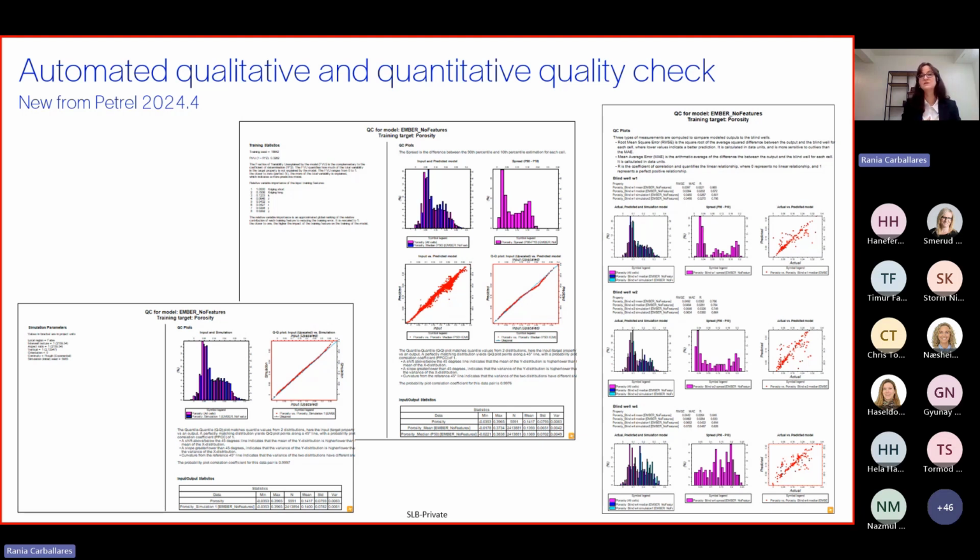We try to open cross plots and plot our properties, the upscaled versus the model, and we try to see how the modeling is going, or open those histograms and try to see, for instance, the porosity for upscaled and not upscaled, and the grid. And it also brings you the statistics information that we typically try to access when we go to the property itself, right-click, go to the settings, and then QC the statistics.